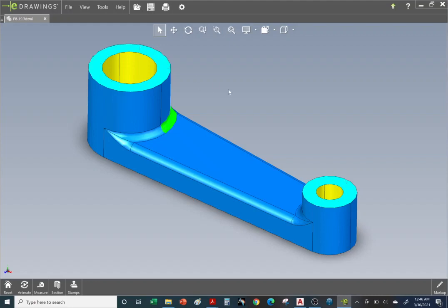So both of these will be parallel, not in the same plane, but they will be parallel to each other, and also in this case parallel to the base, to the bottom, because most likely something needs to attach to these surfaces, or I should say mate up to another part at these surfaces. And same thing with the bottom, most likely it'll have to mate up with the other part and most likely bolt it together. All right, so let's take a look at the answer key.